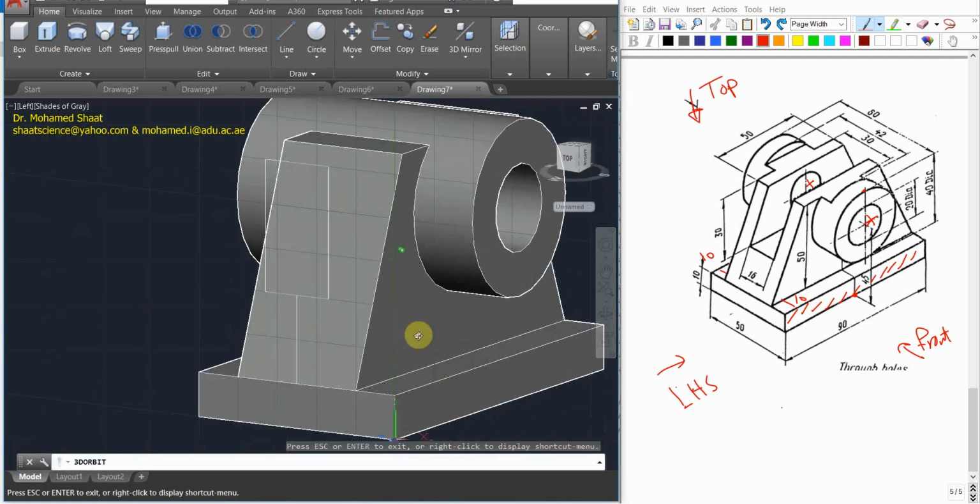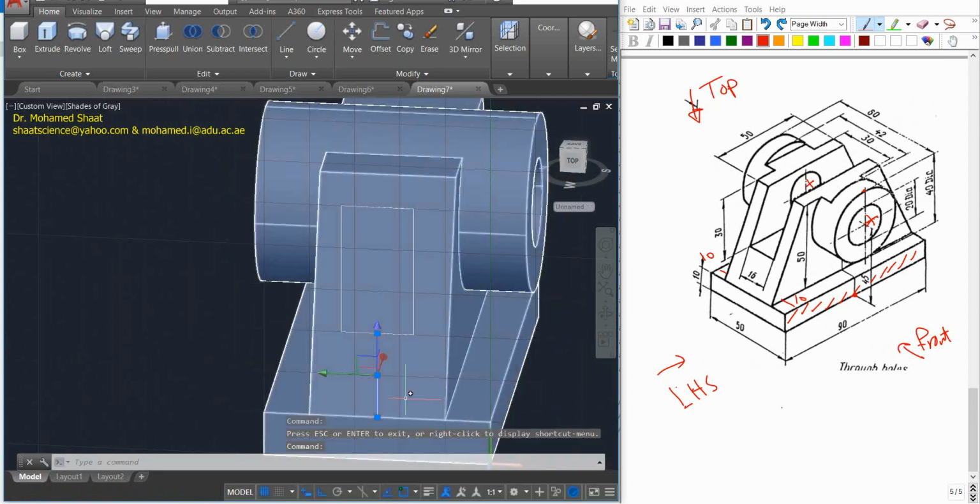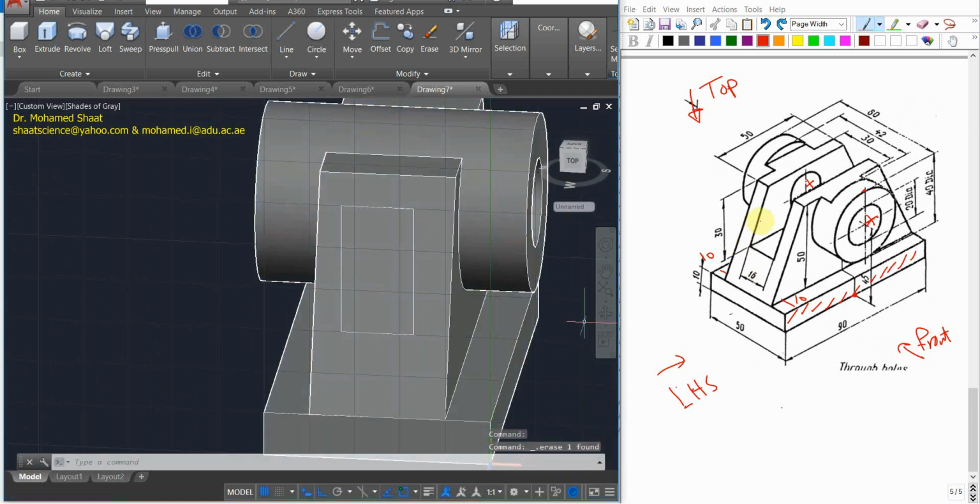So in this case, I'm gonna see the line vertical, standing in this way. Then I can remove this line. So this is gonna give me this rectangular thing, but standing. When you extrude it, it will cut the entire shape. Make sense? Then in the meanwhile, I have to cut some of this cylindrical shape. It should be cut in this way, like there should be something cutting here. So that's why I'm saying that there should be a T-shape, and all of this T-shape will be extended to cut the shape entirely.